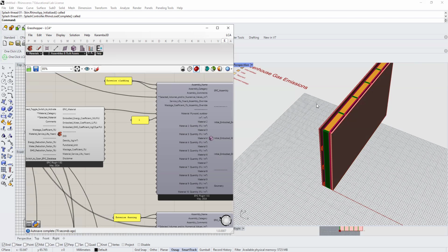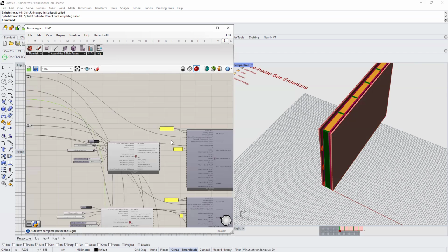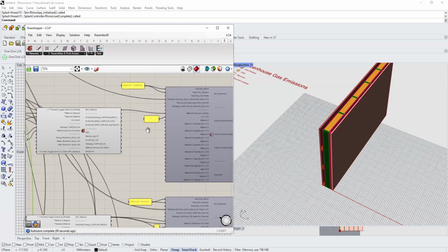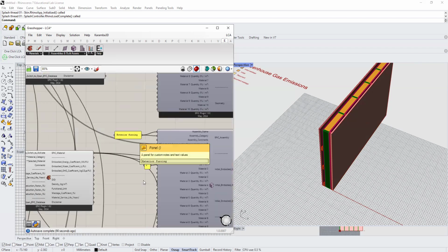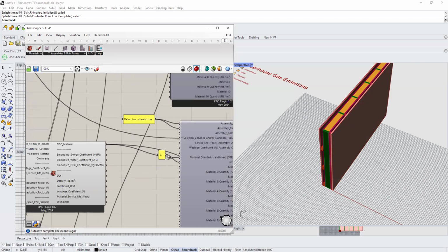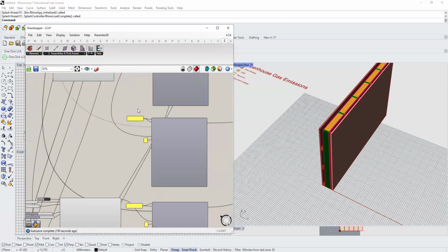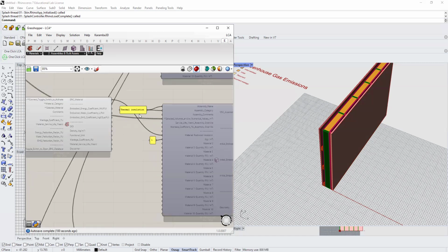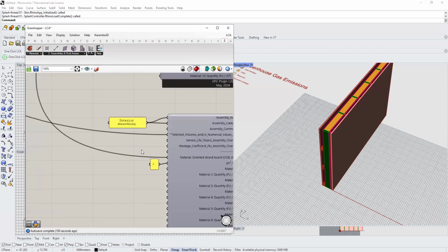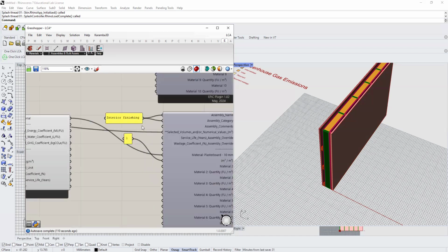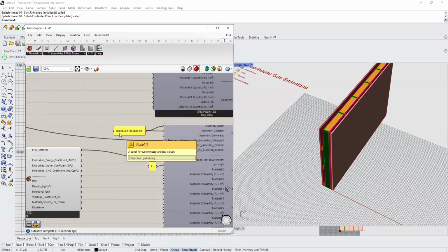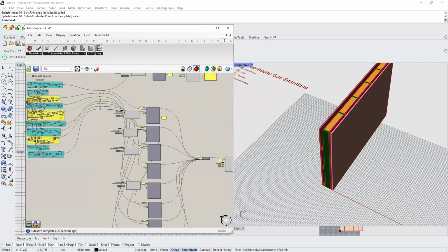So I will call this assembly name an exterior cladding. It is also, I mean, I have just the same category of walls. This one is basically the cladding here. Then the next component will be exterior fairing. Then it will be the exterior sheathing. Then I'll define the studs, then thermal insulations, interior sheathing, and interior fairing, and interior finishing, and also interior painting. That is nice that you can do everything.